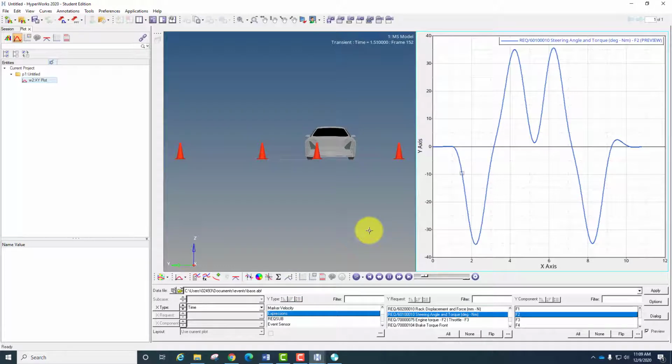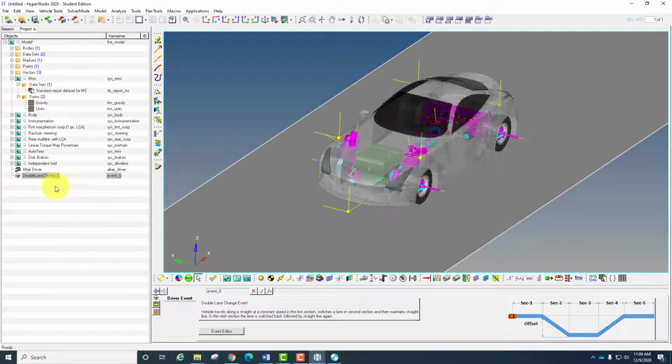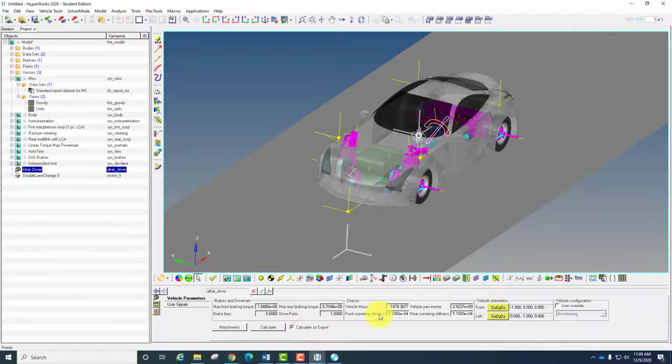And for the lab session, let's say you want to change a parameter. Say you go back to this. Let's say I want to change the cornering stiffness. The cornering stiffness here is 51,000. I want to make it a stiffer cornering stiffness. Let's say I put it quite higher, which is 80, instead of 51.